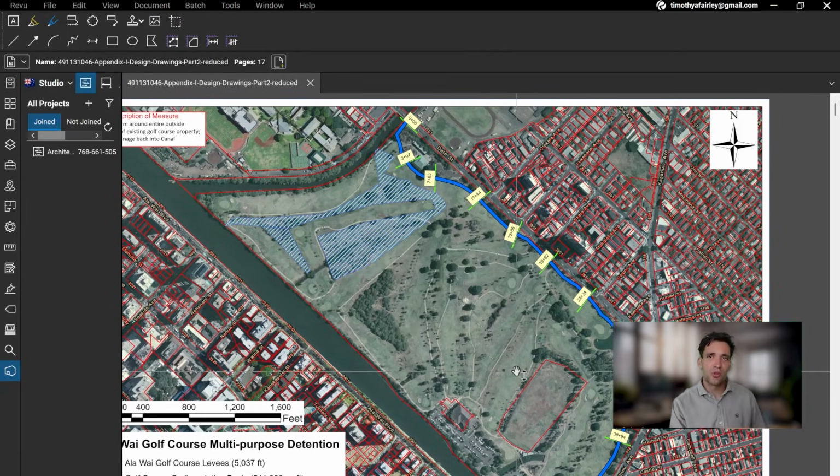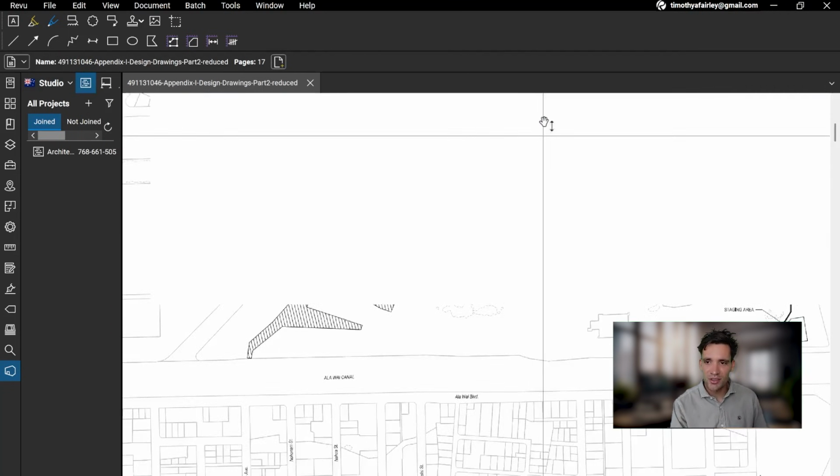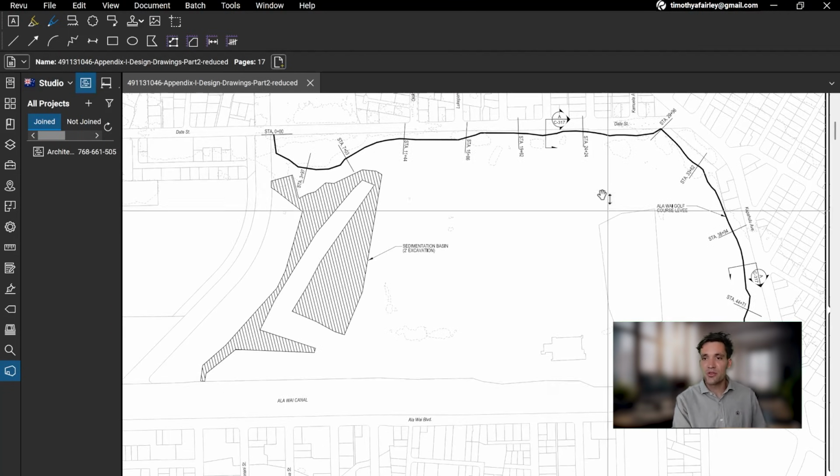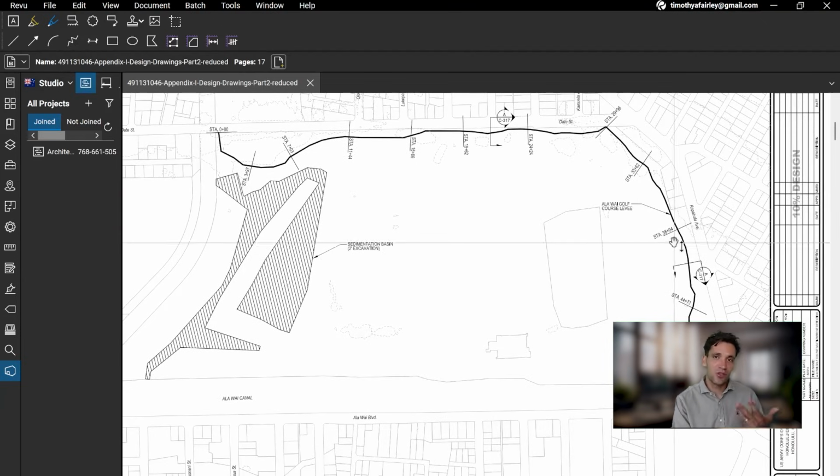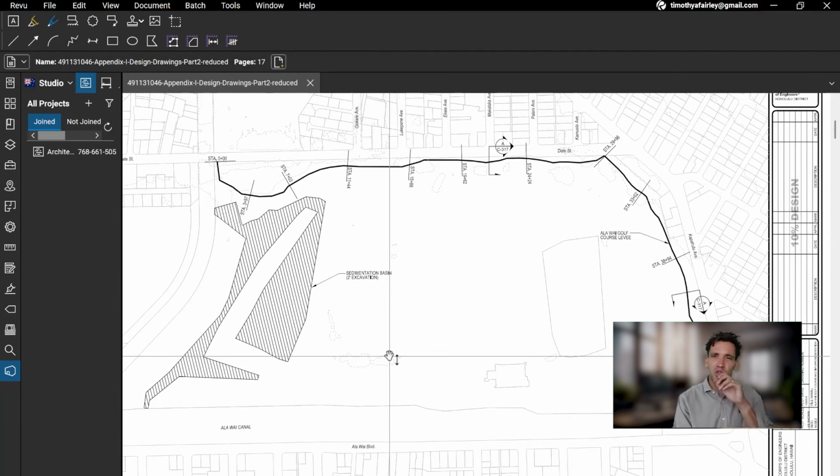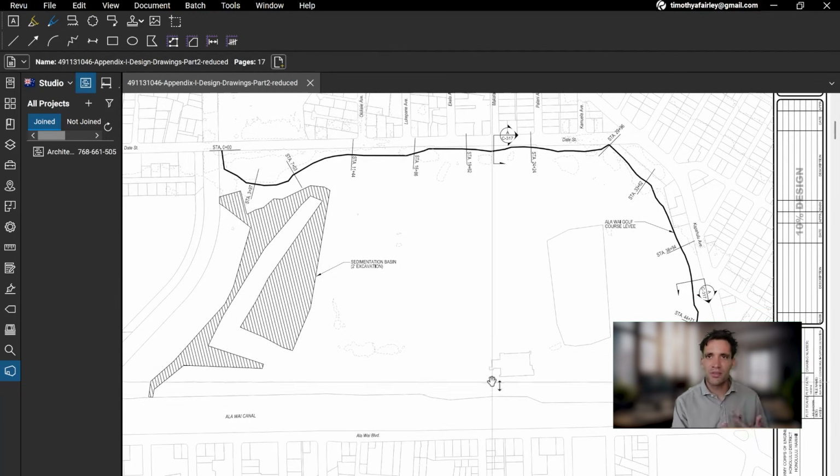I just literally Googled civil construction drawings and got this project. It seems pretty interesting. It covers all the key activities: clearing and grubbing, placement of fill for the berm, compaction, excavation of the basin. I'm not talking about concrete and structural work because I've done that in a separate video and I think it is a separate topic. And I also use Bluebeam for my quantity takeoffs.